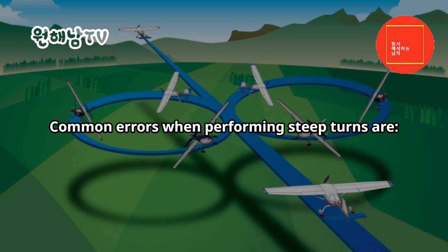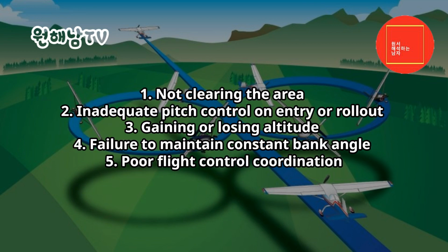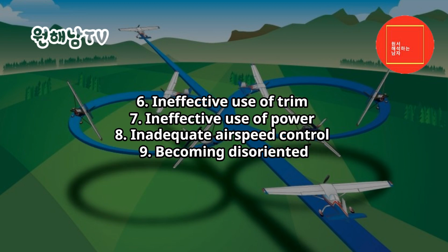Common errors when performing steep turns are: 1. Not clearing the area. 2. Inadequate pitch control on entry or rollout. 3. Gaining or losing altitude. 4. Failure to maintain constant bank angle. 5. Poor flight control coordination. 6. Ineffective use of trim. 7. Ineffective use of power.